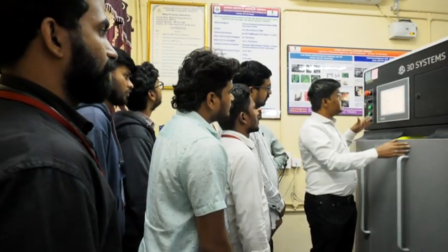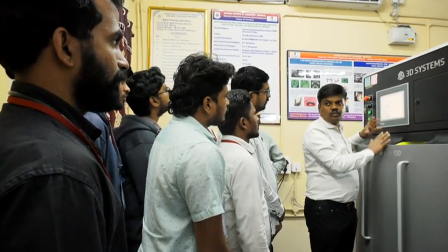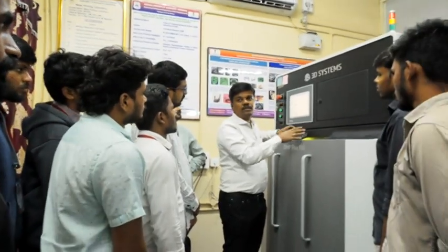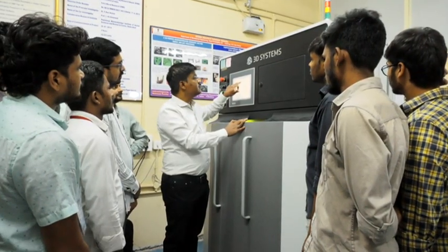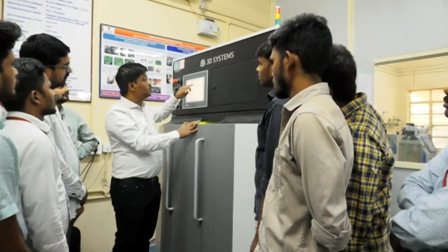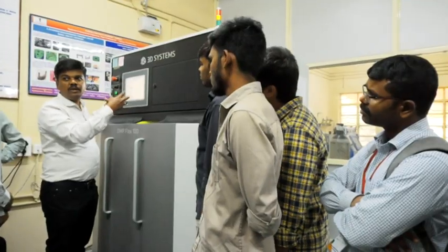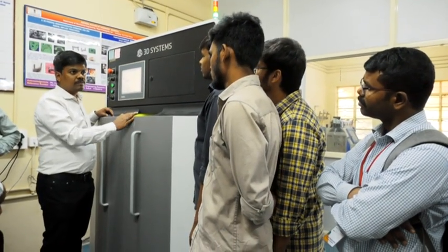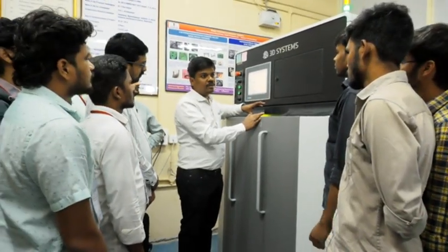Then, for the programming we feed, we have to purge argon gas completely into the chamber. We need to maintain the ppm level so that we do not oxidize our part during melting. That's why we have to maintain the O2 level. If you see here, it is at 3 ppm. If it goes above 1000 ppm, the argon will purge again. The system is attached to the argon gas, and the complete chamber is argon, so purging takes place to maintain the chamber.